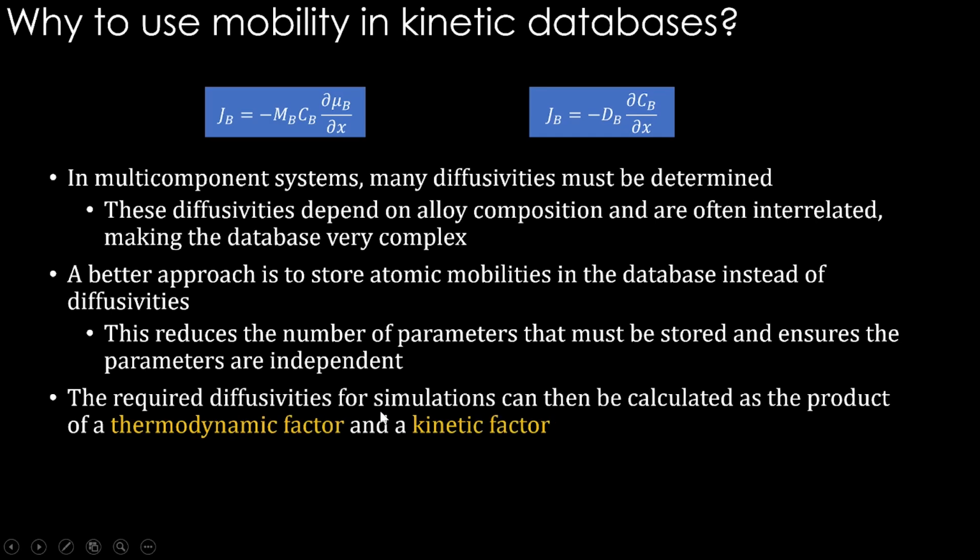The required diffusivities for simulations can then be calculated as the product of a thermodynamic factor, which comes from the thermodynamic database, and a kinetic factor, which comes from the mobility database. So eventually diffusivities will be calculated from that. We will see how to use mobility kinetic databases shortly. At that time I will explain more on this particular aspect.